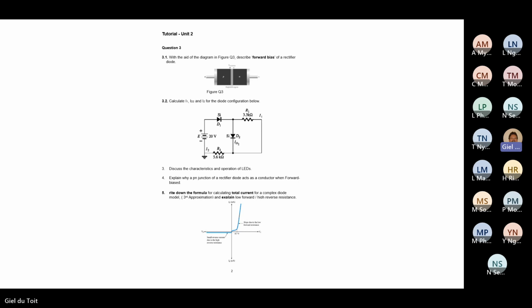So what we have here is on this diode, we've got 0.2 volts. I'm going to write 0.2 volt. Sorry, 0.7. What am I writing, guys? 0.7 volts. The 0.7 volt over the diode will fall over that resistor. So what will be the current through that one?